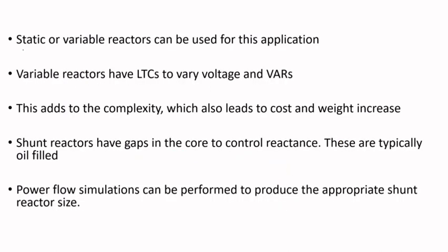It depends. You can install static reactors, in other words, the reactance is either in or out. The entire reactance, so you cannot do increments or stages. Or you can have variable reactors. In other words, you can change the reactance as the voltage changes. Because sometimes you don't want the entire reactor to be in.